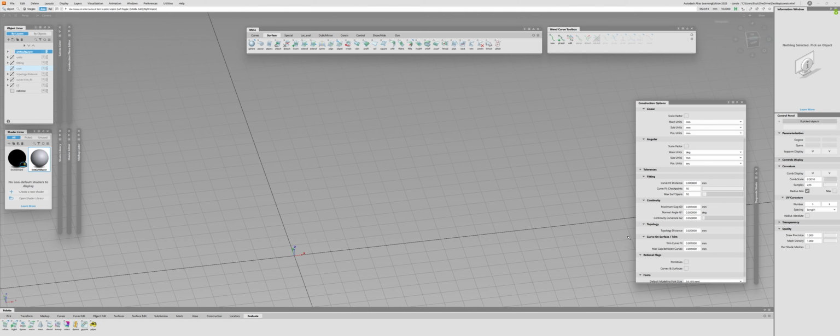So it will be 0.01 millimeter instead of 0.001. So what I mean is that it will be like this for exteriors, and probably 0.1 for tangency and, in most cases, 0.1 for the curvature as well.